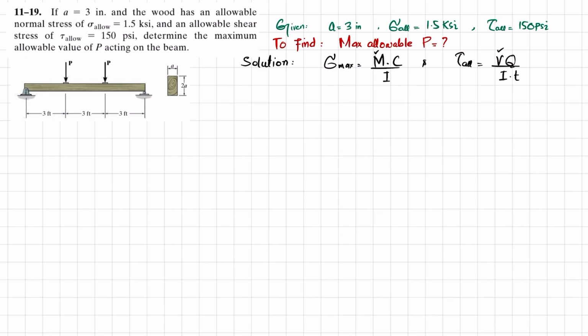For that I will need the reaction forces if we remove the supports. Definitely there will be a reaction force. Let this be R1 at point 1. If you remove this roller support, you will have a reaction force R2, and let this be point 2.